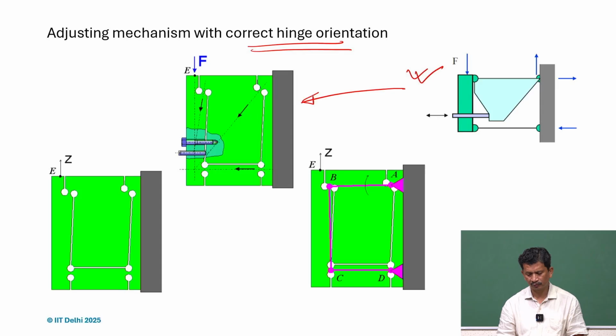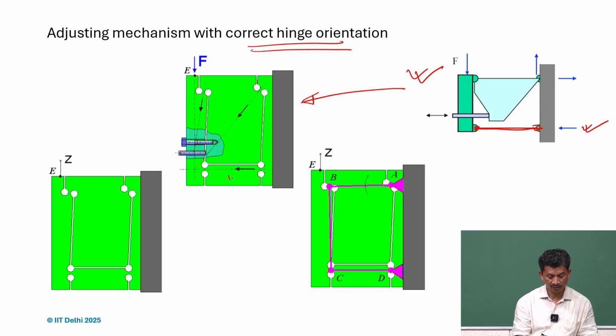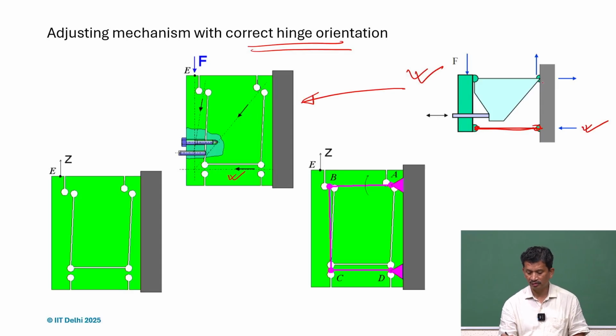So what is required is we have to do the force equilibrium. So write the forces. What we realize is this is the two force member. If we take this, the direction is known. In that case, under equilibrium, there will be only this force, right? Either in tension or compression. So that force is known. This part is the three force member. So one force will be at this part, and then one here, one at the support hinge, and one external force also acting here.